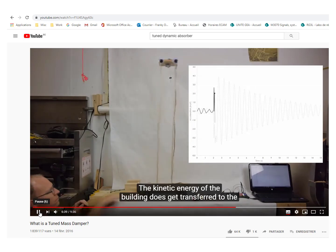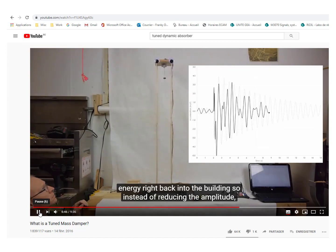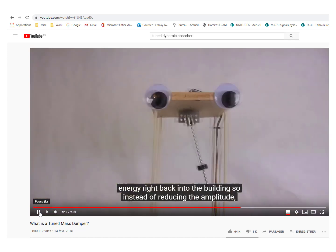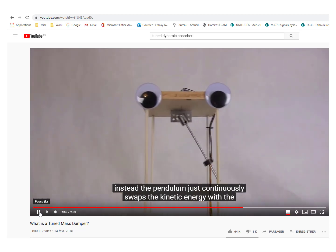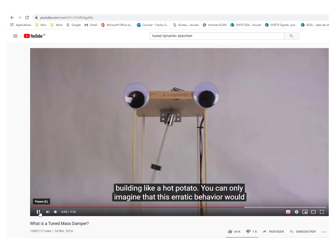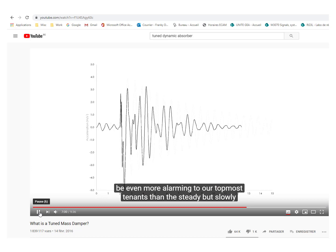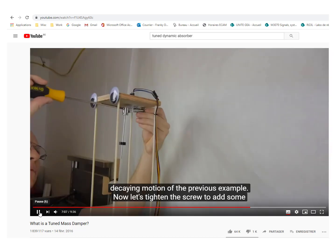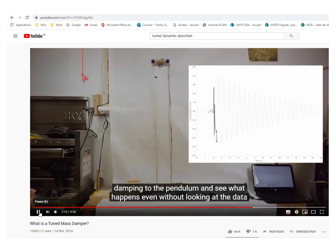The kinetic energy of the building does get transferred to the pendulum at first, but because there's no damping, the pendulum transfers the energy right back into the building. So instead of reducing the amplitude, instead the pendulum just continuously swaps the kinetic energy with the building like a hot potato. You can only imagine that this erratic behavior would be even more alarming to our topmost tenants than the steady but slowly decaying motion of the previous example. Now let's tighten the screw to add some damping to the pendulum and see what happens.